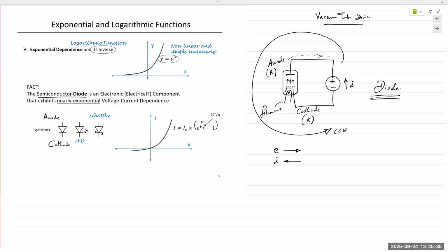And so holes are the exact opposite of electrons. It's not a physical device or a physical quantity per se, but it's a particle in its own right. Okay, so an electron is an actual subatomic particle. A hole is a representation of the absence of an electron, but for theoretical analysis, we treat that hole as a particle in its own right with positive charge.